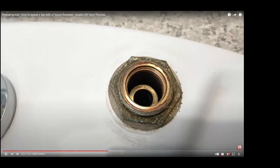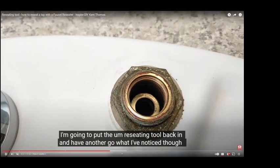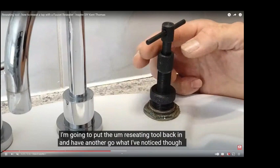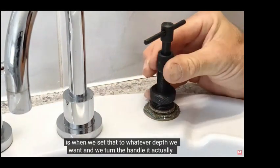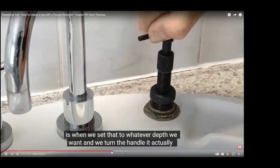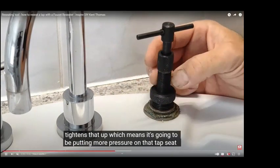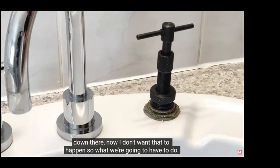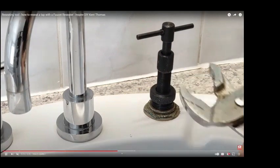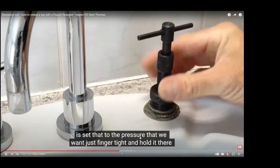You want to blow as much of that stuff out. Should be dead smooth. You can see his one looked a bit lumpy, and that's because he's ground too deeply with it instead of just skimming it. Potentially what he's doing here is he's going to wreck the whole seat and screw the whole tap up. He'll probably get away with it, but if you did that every time, you're only going to be able to reset it about twice before you've stuffed it.